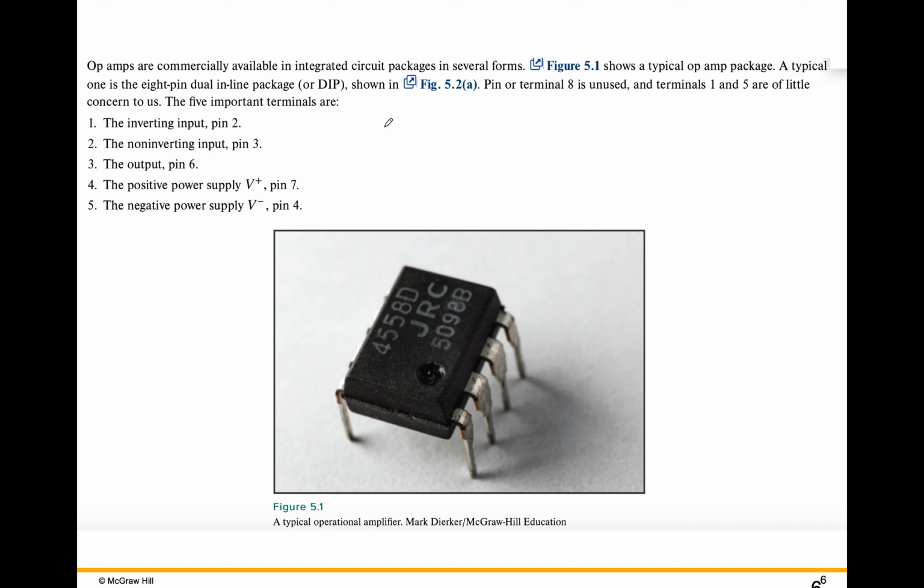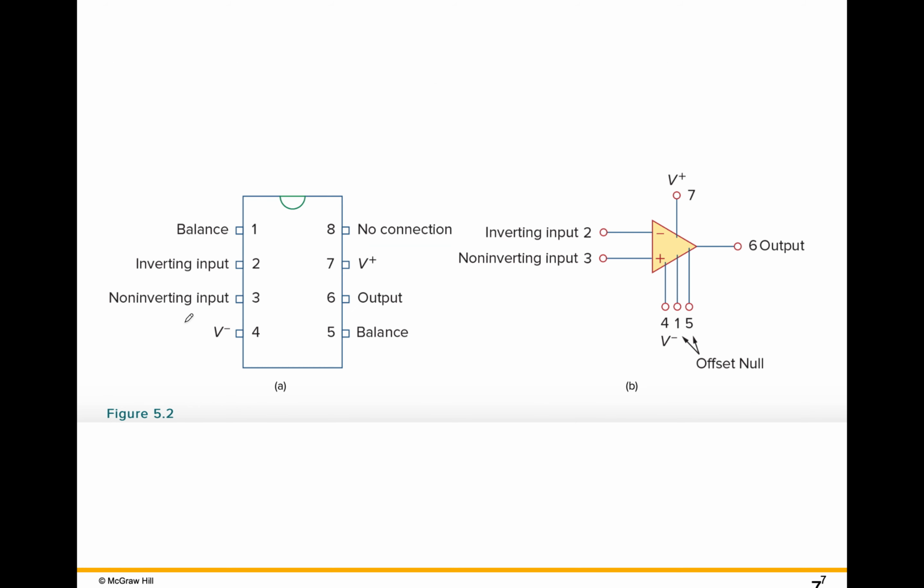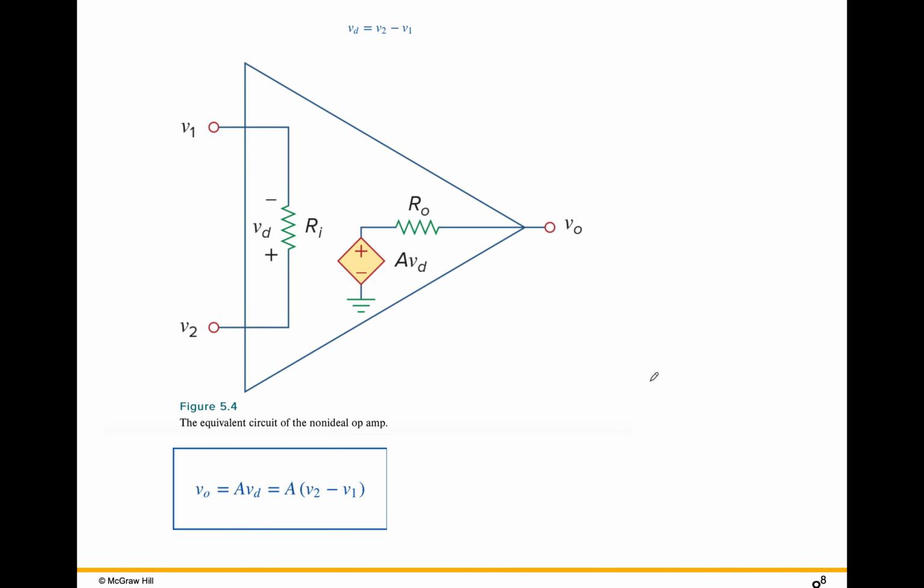They're typically used to tweak things to get you a balance on your DC voltage, as well as some other things in the lab to make the op amp perform like you want it to perform. Because as with all electronic components, they have a certain accuracy to which they're manufactured, and they're not all going to be 100% identical. So this is just a slightly bigger picture taken directly from your textbook that has a little less noise, where you can see the pin connection on the op amp, and then a bigger picture of that op amp schematic.